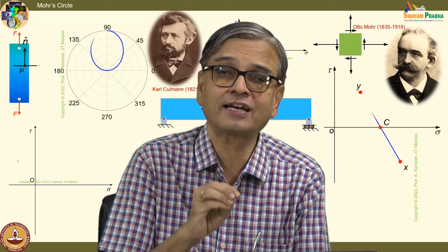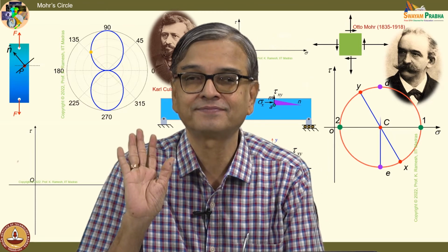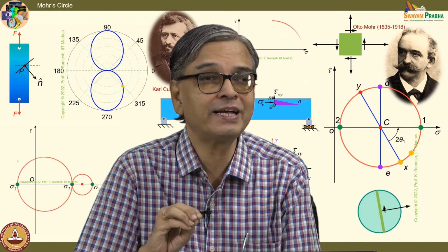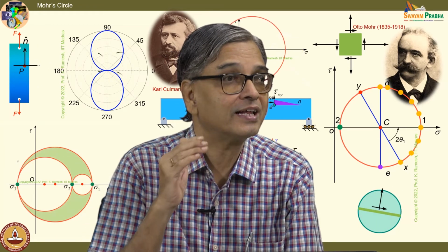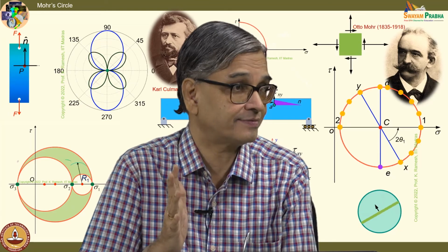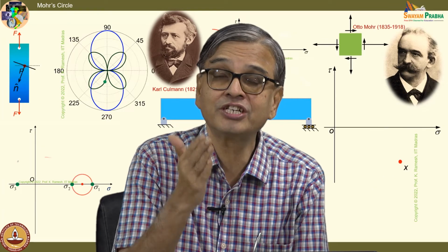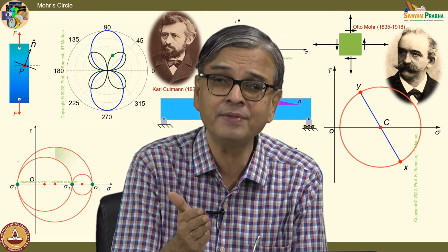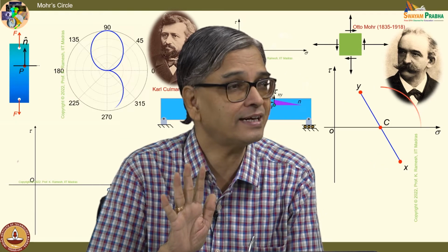Suppose I say for the current discussion, it fails by maximum shear. It does not fail by the critical value of normal stress, but the critical value of the shear stress. So, whichever plane orientation the shear stress is maximum, you will have material separation along that plane. Is the idea clear?